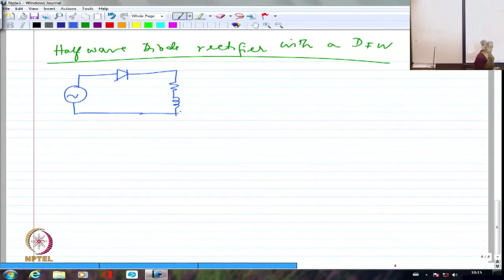Let us say I'm going to connect a diode like this, which is across the load, which I would call a freewheeling diode, which will be able to take the trapped energy across the inductance. It will essentially pass the current because of the trapped energy in the inductance. So we call this a freewheeling diode. It is essentially simply going to circulate the current. It doesn't have any other job other than to do this.